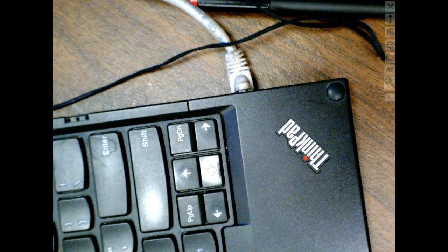Some of them are labeled. I want y'all to see this. This is one method we use to label electronic components. So y'all look on there, 331 on there somewhere. What do you think that's telling you? 33 and 10. So basically, it's kind of like a color code without the colors. So 331 is 33 and 10. You understand? No, not red. Orange. This would be an orange brown if it was a color coded resistor. Remember, it starts at 0, Kareem.